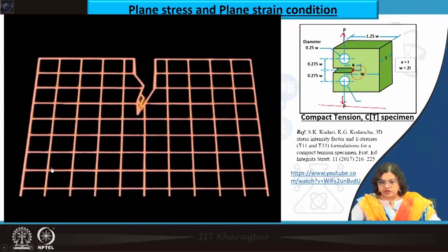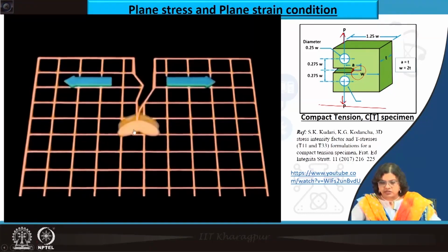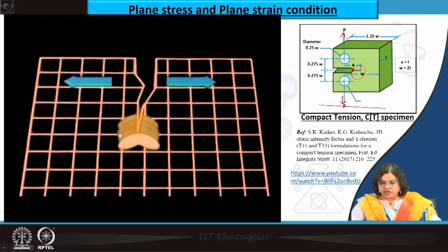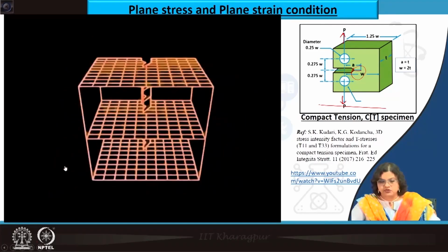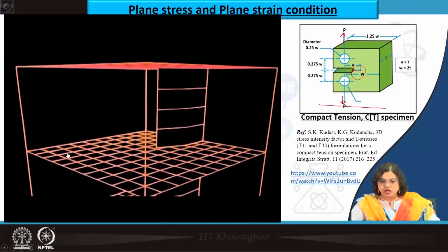Essentially, when we are having the stress along this direction, the crack grows in the perpendicular direction, and it forms a plastic zone, which eventually grows as we are applying higher and higher stress values. And when it grows, it actually leaves a wake of plastic zone on the crack side, and that is dependent on the plane strain fracture toughness of a material. Now, plane strain fracture toughness varies from one material to another.